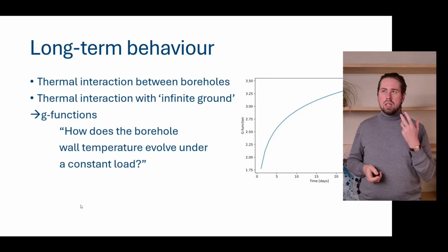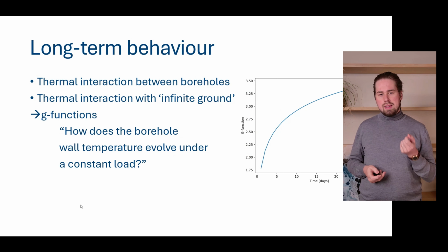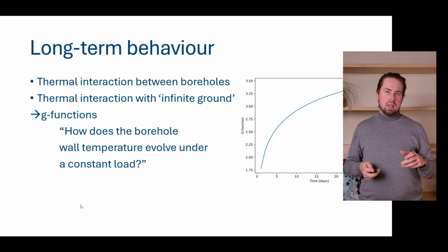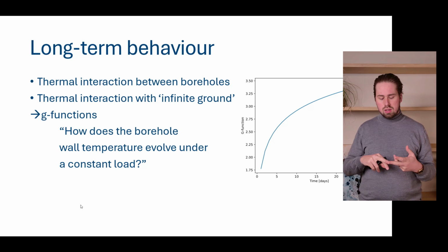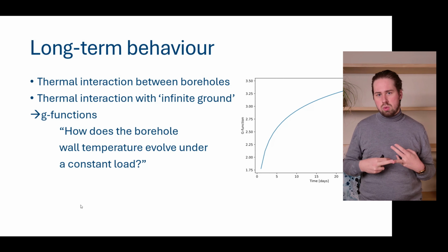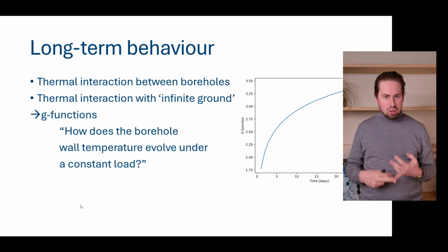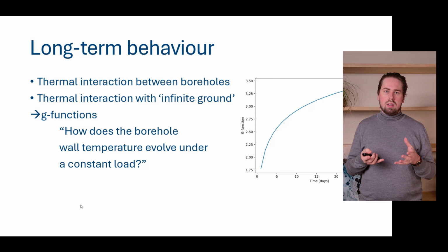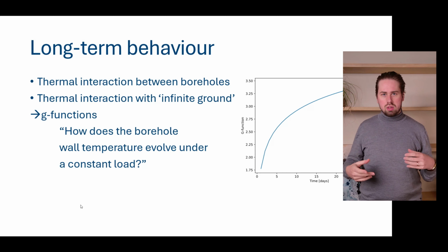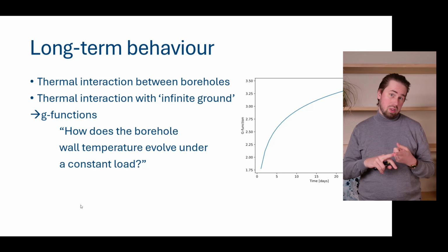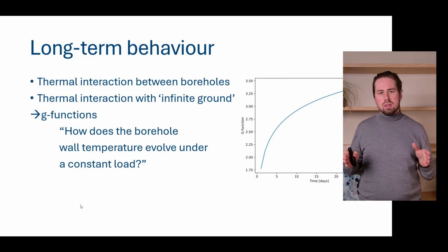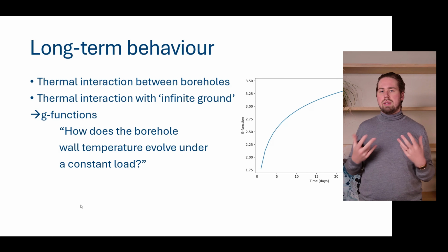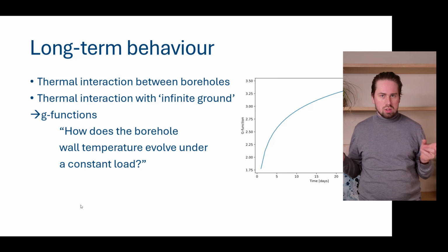Now, if you think about bore field physics, it's actually a really complicated problem. To start, it's three-dimensional, a volume in the ground. It's transient, because it changes over time. And it's a heat diffusion equation, so it's a really complicated mathematical problem. Conceptually, in a bore field there are different boreholes, and they all interact with each other. That's one complexity. The other is that the ground does not stop at the edge of the bore field. It continues, so there is also this interaction with the infinite ground.